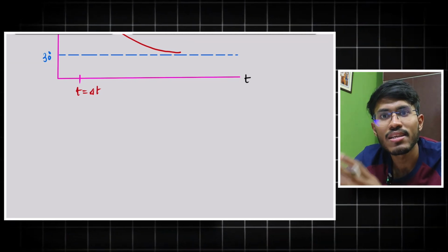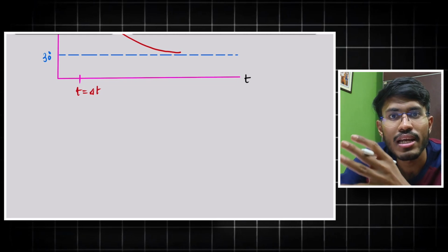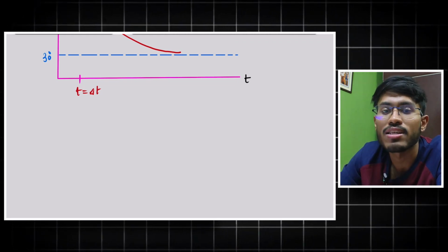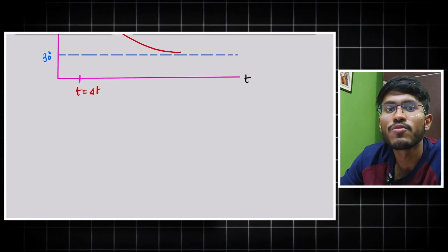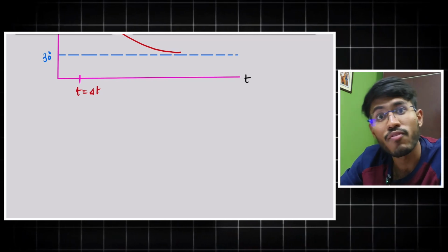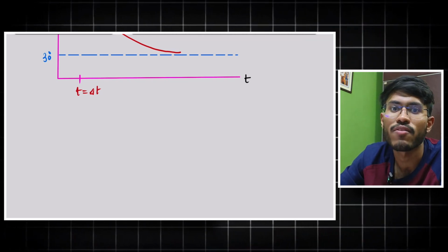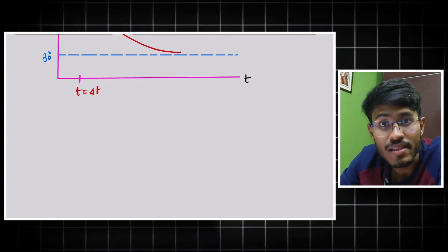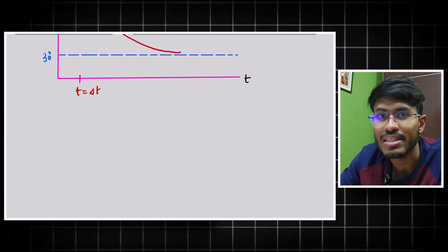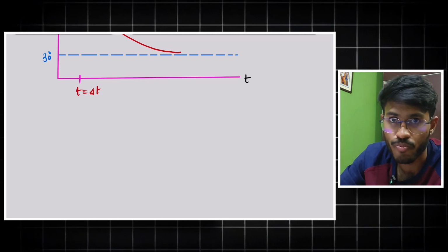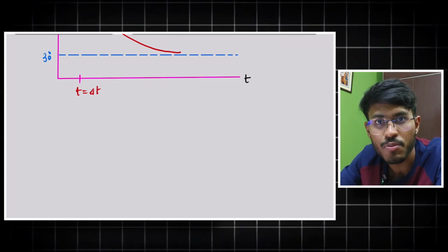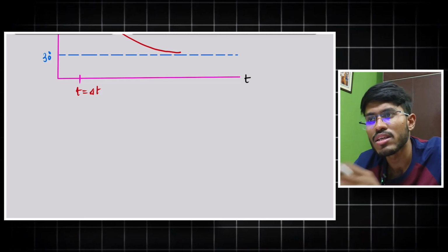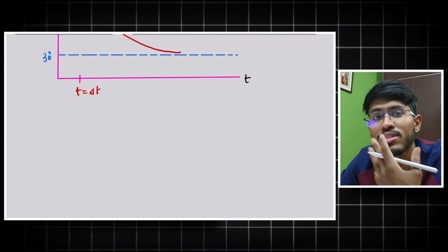And the heat transfer is actually taking place from the surface. So if the surface area is more, more heat will be transferred. And if the volume is more, it has the capacity to store the heat. It has the capacity to store the heat if it has a very large volume. And if the surface area is more, then the heat transfer rate is more. So that means these two are actually opposing each other.